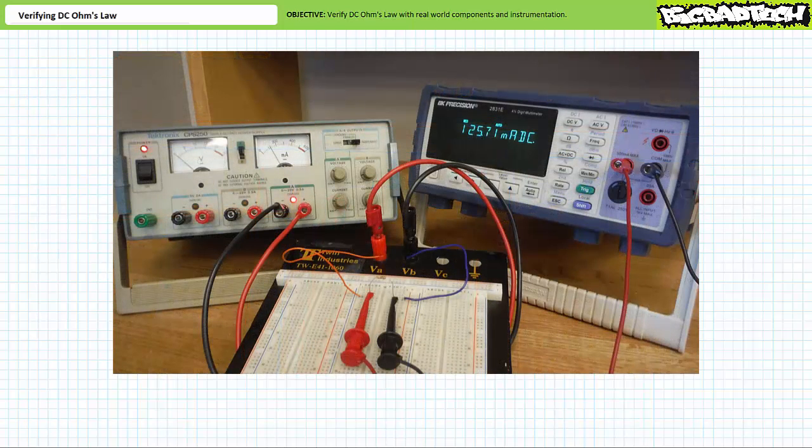Here the DC power supply is current limited to a maximum of 125 milliamperes. When we turn on the power supply, an ammeter incorrectly configured in this fashion demonstrates roughly 125 milliamperes, our permitted maximum, flows through the ammeter. The source indicates it's in an overload condition by illuminating the overload LED. Again, we've current limited this source to 125 milliamperes. If this source was capable of producing, let's say, 100 amps, all 100 amps would be diverted through the ammeter installed in such a fashion. This is a surefire way to destroy the device and those in close proximity.